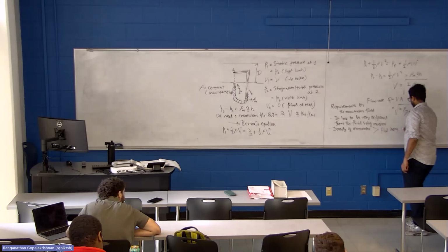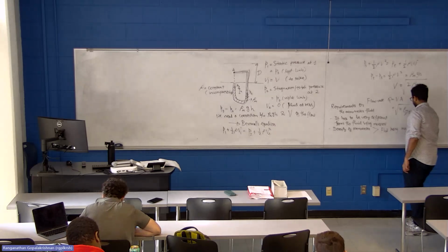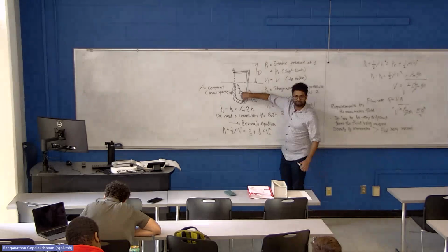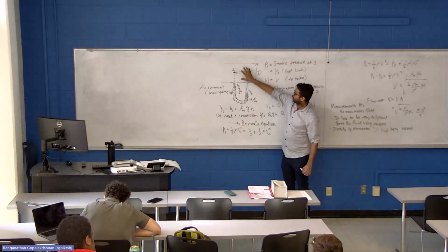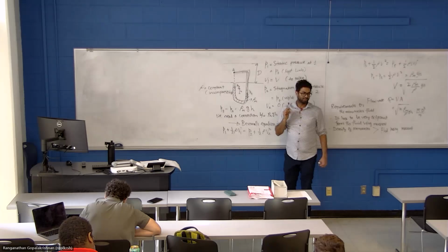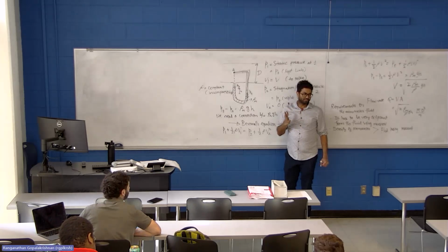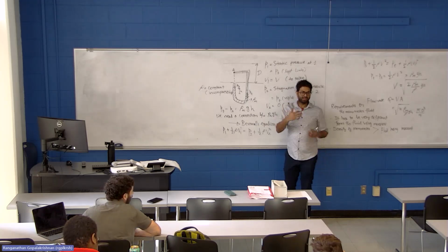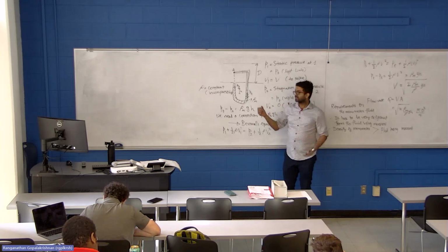Not only is it about density, what else? What if you have, let's say, this is water, okay? And the fluid you are trying to measure is carbon dioxide. What is the problem? It will just dissolve in the water and start vanishing from the flow. It's like a siphon.